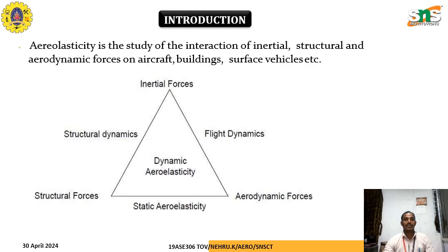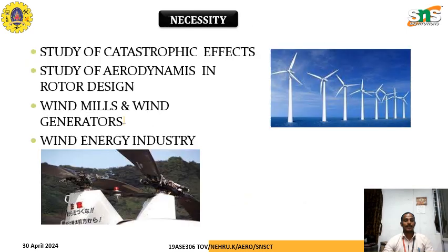Introduction: Aeroelasticity is the study of interaction between the inertia force, structural force and aerodynamics of aircraft, airplanes, buildings, and surface vehicles. This triangle is a combination of inertia force and aerodynamic force, which makes the flight dynamics, and inertia force and structural force, which makes the structural dynamics, and structural force and aerodynamic force, which makes the static aeroelasticity, which is the outer boundary. Inside, the combination of all these three, inertia force, structural force, and aerodynamic force, makes the dynamic aeroelasticity.